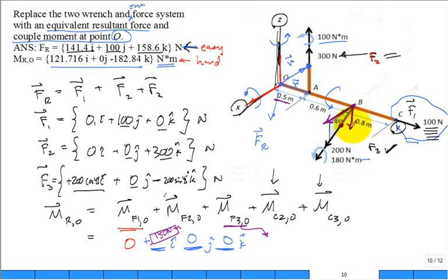True? And then, I know maybe at some point you say, forget it, let's trust the math and do the cross product. But this F3 in the Z will not do anything about the Y, will not do anything about the Z, but it will do something about the I. That F3 in the Z will contribute a perpendicular distance of 1.1 meter, and it will be a negative sense of rotation.